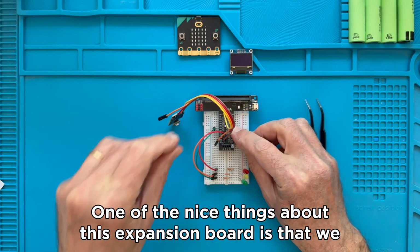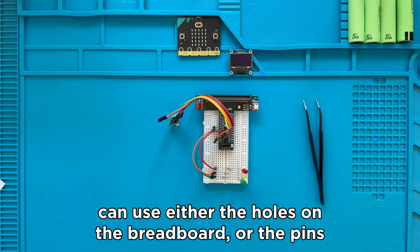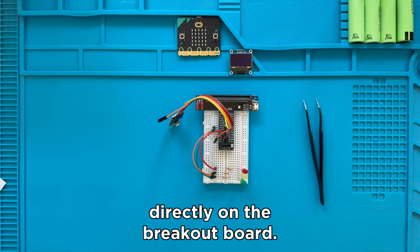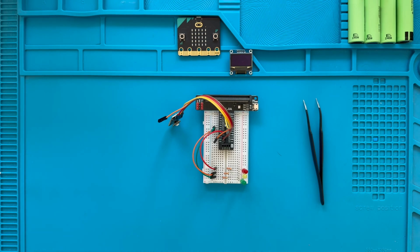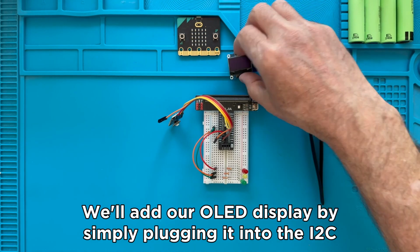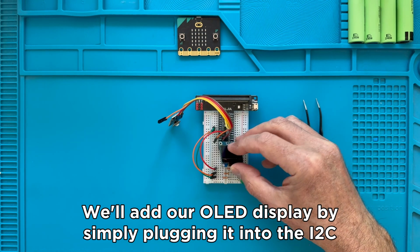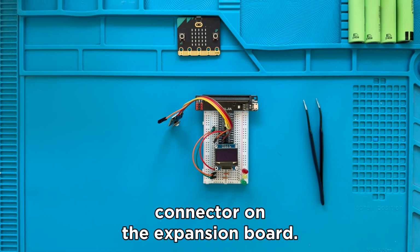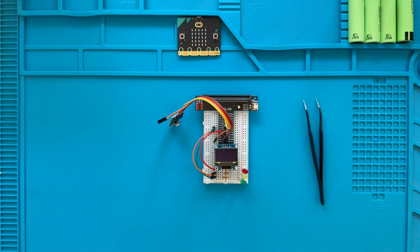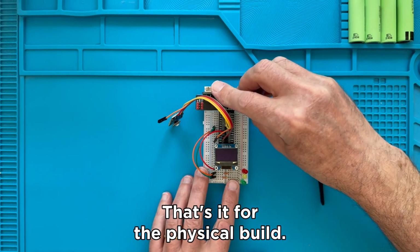One of the nice things about this expansion board is that we can use either these holes on the breadboard or the pins directly on the breakout board. For the finishing touch, we'll add our OLED display by simply plugging it into the I2C connector on the expansion board. That's it for the physical build.